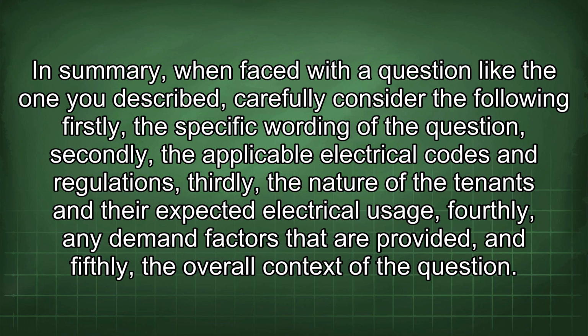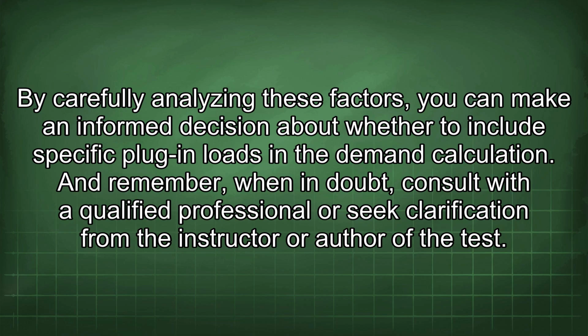Firstly, the specific wording of the question. Secondly, the applicable electrical codes and regulations. Thirdly, the nature of the tenants and their expected electrical usage. Fourthly, any demand factors that are provided. And fifthly, the overall context of the question. By carefully analyzing these factors, you can make an informed decision about whether to include specific plug-in loads in the